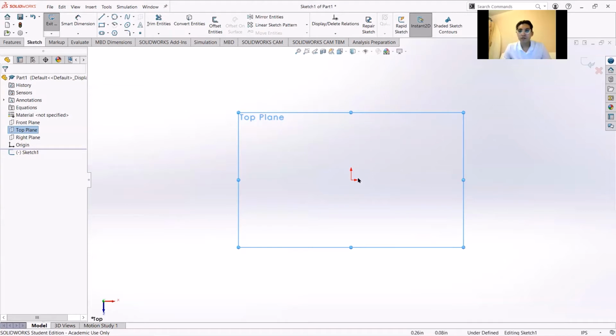So once you've clicked sketch, you'll get this little dot when you hover over these two arrows, the origin arrows. We're not going to click on it now. We can, but just know that that's there, because when you see the circle when you hover over it, that means you're on it. So if you're very close to it, but it doesn't show up, you're not necessarily on the origin. That's really important if you're trying to center your part.